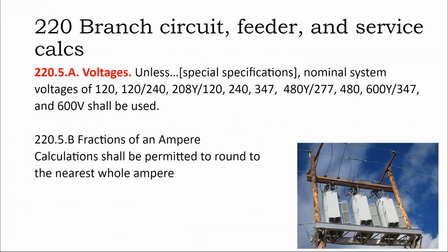So we have a definition of voltages, and I would just remind you that when we talk about voltages, we're talking about nickname voltages, and the actual voltage versus the nickname can vary rather substantially. It's common for rural electric grids to operate at higher voltages than this to get 124 volts per leg and get up to 248, sometimes 250 volt readings. So these voltages are kind of nickname voltages.